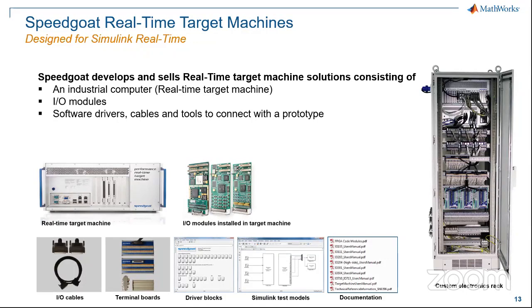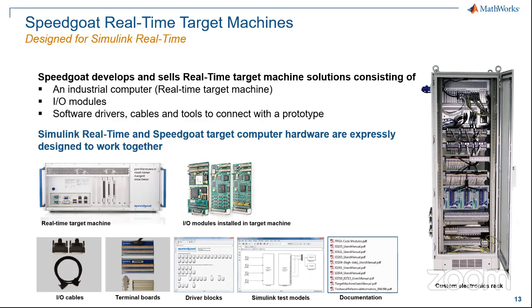This is a very powerful machine, with an Intel Core processor and many I/O channels for testing serial communication in real time. And for people interested in running at a higher switching frequency, like megahertz and above, the Speedgoat machine also provides a customized FPGA to generate HDL code if you are interested.